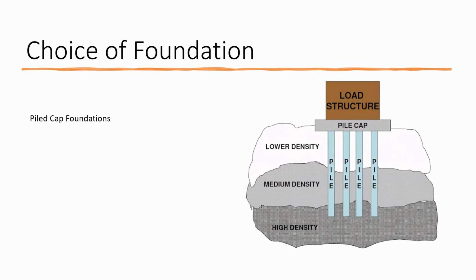Different options. I believe that either the pad or pile foundation would be the more suitable option in this instance, as they both will be able to distribute the concrete building loads and will work well with the ground conditions highlighted in the brief. Both the pile and the pad foundation should be able to cope with the demands of the building loads and ground conditions in order to create a strong and stable footing for the building to be erected upon, and I have opted for the pile foundation.